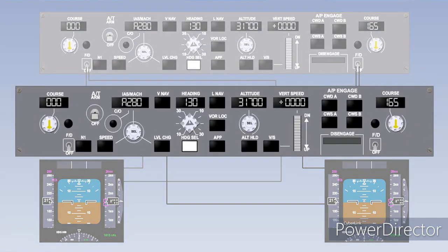When both flight directors are being used without the autopilot, then the one that was selected first becomes the master. This is indicated on the mode control panel. The flight director modes selected are controlled by the master flight director and are displayed on both primary flight display